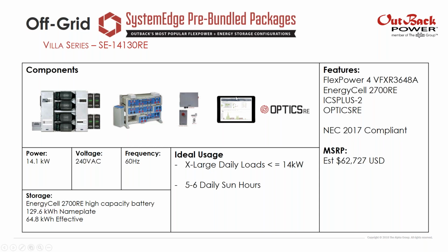The right size combiner box, again, meets National Electrical Code, incorporating rapid shutdown and arc fault. It shows one of these boxes, but you actually get 4 of them, one for each charge controller. This is a 48 volt DC system, so each charge controller is good for 4K worth of solar. So this system can handle a fairly good size array at 16 kW.